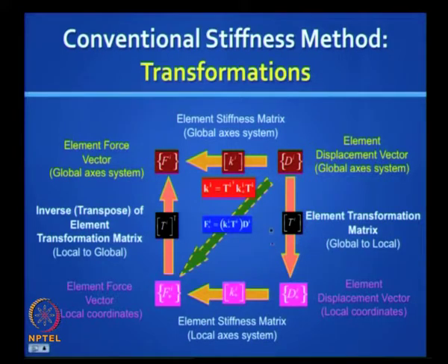First, identify the coordinates, develop the TI matrix, develop the element Ki star matrices, do this operation first, then do this operation, put the linking coordinates and assemble your structure stiffness matrix. First assemble your matrix element wise and then assemble the structure stiffness matrix. After you solve this equation and get the unknown displacements, directly use this to get your member end forces.